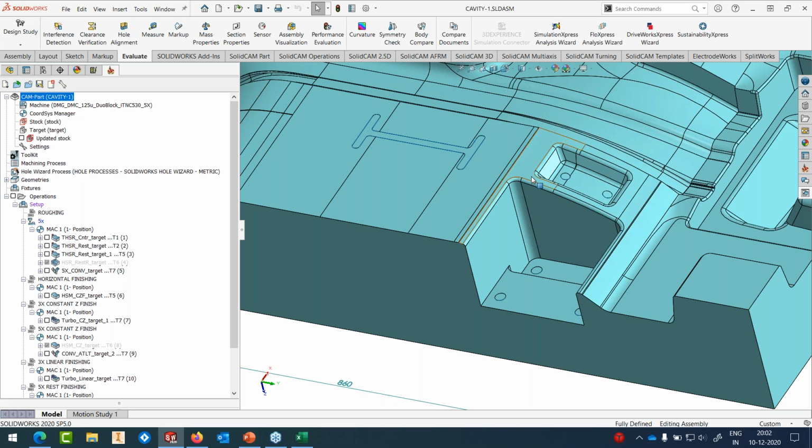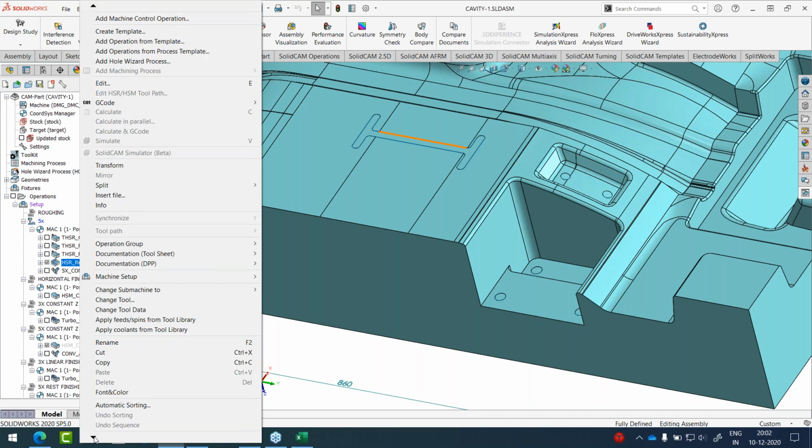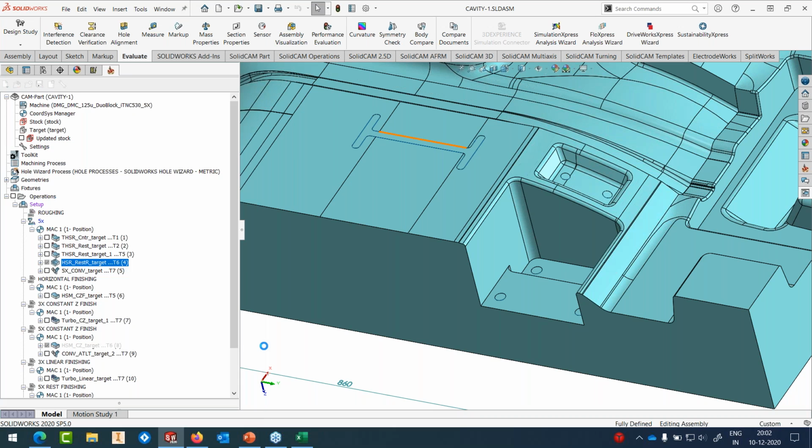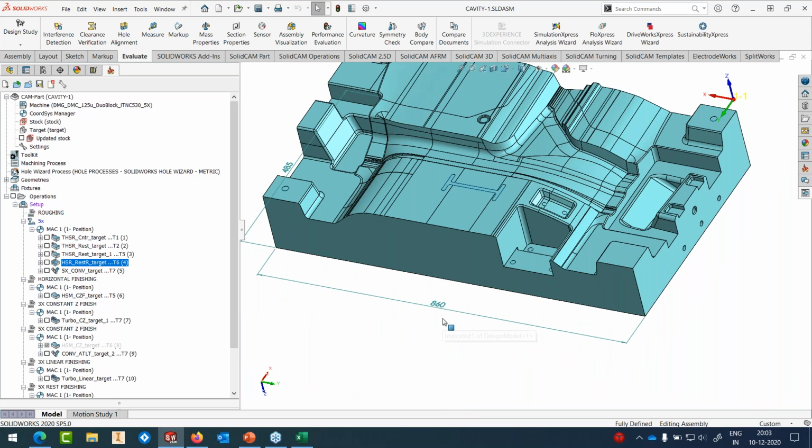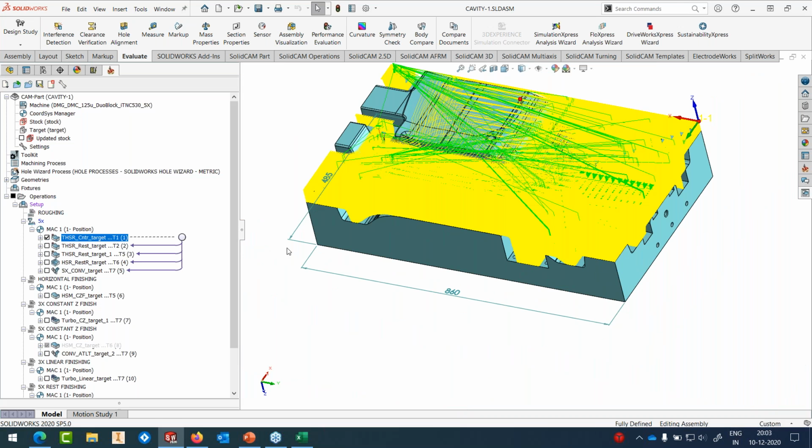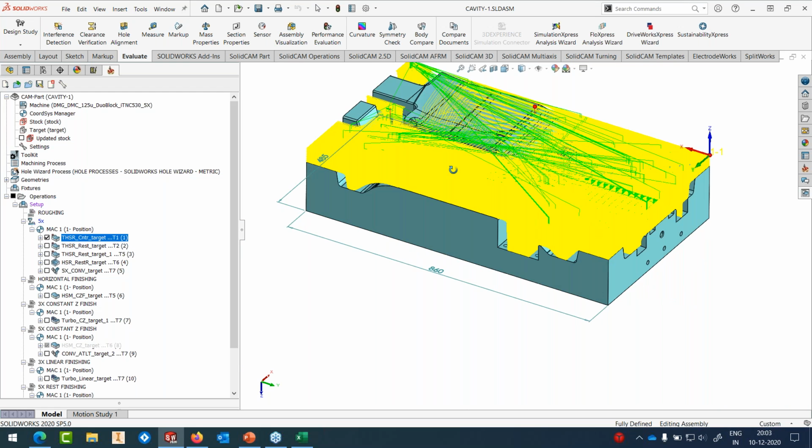And if you have a 5-axis machine, you should use the power of SolidCAM's functionality to take a 3-axis toolpath and convert it to 5-axis. So what I've done here is, if I unsuppress this toolpath here, I've done the rest roughing. I'll just show you what all has been done before that so that you get a gist of how this comes up. I first used a 50R3 bullnose to do the roughing of this part.